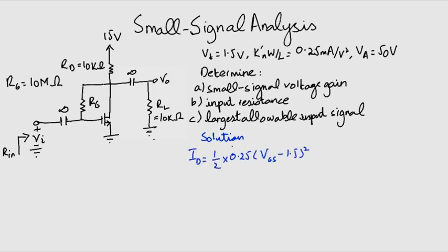In the drain current equation, we have neglected channel length modulation for the sake of simplicity. The Early voltage given to us, 50 volts, is actually for the purpose of calculating ro. We substitute VGS by VD by noting that the current through the gate is 0 because of the large 10 megohm resistance. So essentially, drain and gate are at the same potential, and since the source is shorted, we can simply replace VGS by VD.